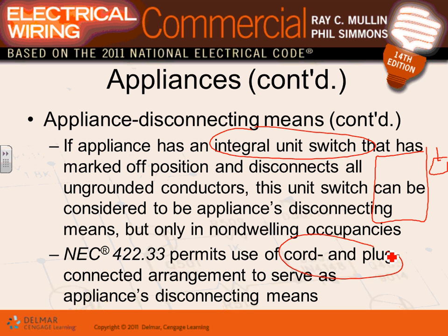Most of the major three-phase equipment, guys, is hardwired. But if they're plugged in, remember, the plug acts as a disconnect means. And you know what they do? What OSHA requires for certain appliances, guys, bigger equipment, is that you unplug it.